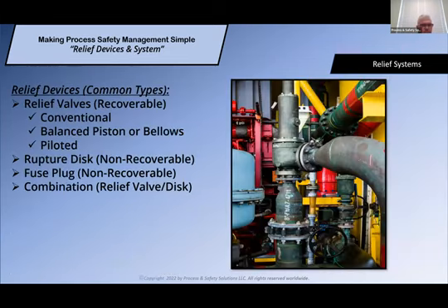issues right now. So we're going to look at 3 different types of relief devices today. I know there are others out there, but we're going to look at just the more common relief devices. First are the relief valves that are recoverable, and what I mean by recoverable is they open and they close. Those are conventional, and what we mean by that is it's just a spring-loaded valve and nothing fancy. We see spring-loaded valves in just about everything. Even the hot water heater in your house has a spring-loaded type of valve. They are what we would call a conventional spring-loaded valve.